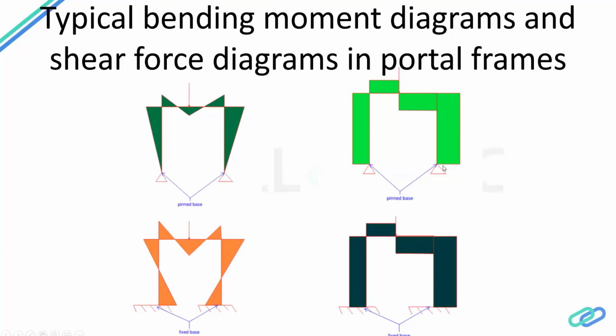And this is the shear force diagram that we see here for the column. So even though we are applying a vertical load, we're still seeing a horizontal force here. The reason is that when you apply this kind of load, the columns want to move outwards. But since this is a pinned support, it restrains that movement, and therefore it develops those reactions in the horizontal direction.